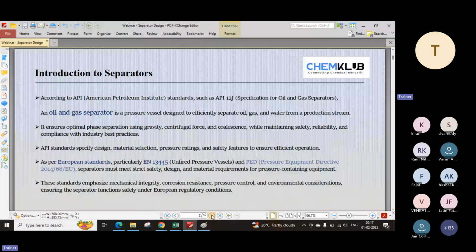Majorly, we use tanks to separate the oil and liquid, where the separation occurs because of sedimentation or gravitational force. However, when we have separators where continuous feed is coming, the feed is separating into gases, light oil or light product, and heavy water, and this is continuous. Whereas in the case of tanks, we are giving much residence time. Okay, that is the major difference we can say.